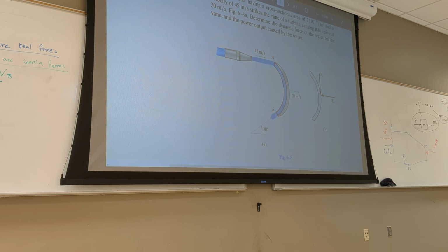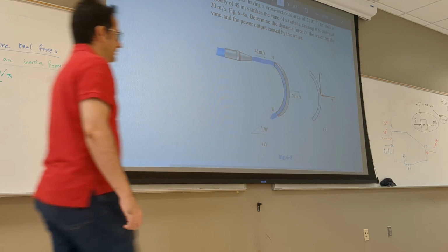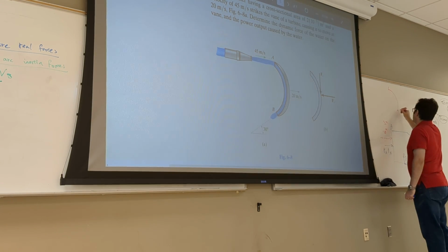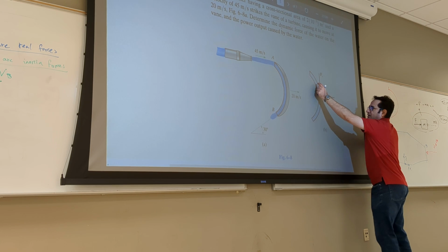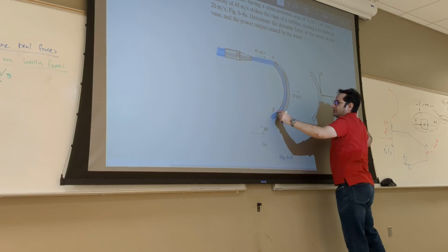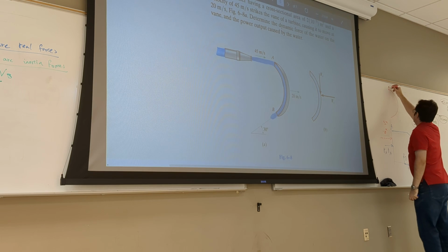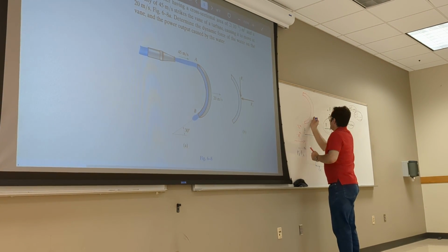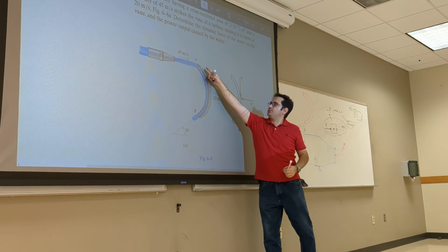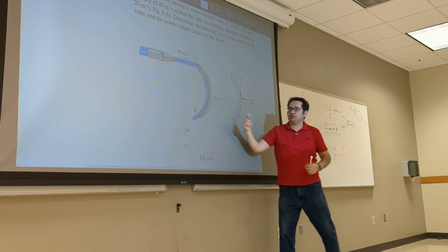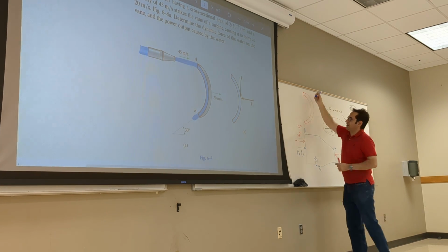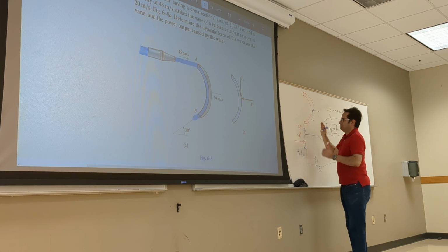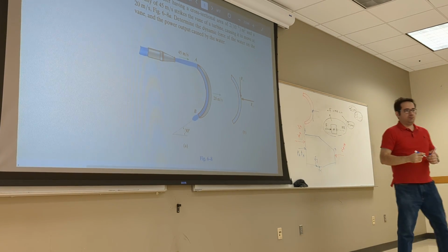If I want to include the inertial load, what do I have? Let's see right here. So that's my control volume, you see? It's around only this part of the fluid. Do you see that? So if I draw the control volume, of course there is a force coming from this object, the curvature, on the fluid, which is actually a distributed load. You see it's everywhere, but you put the net result in one point. That's fine. But what are the other distributed loads?